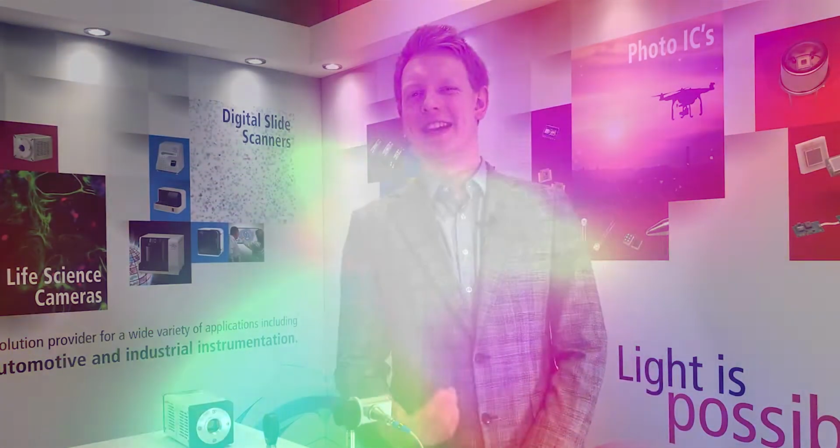For sure. As a sales engineer in our industrial group here at Hamamatsu, one common application I encounter is the monitoring of laser beams. Generally, customers are interested in determining the profile and size of the laser beam. If these laser beams extend beyond 1.7 microns, extended InGaAs can be used for these measurements. To demonstrate this principle, I will use one of our extended InGaAs detectors.